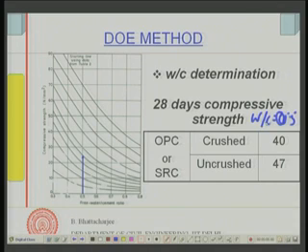The best way is to do a trial mix, and in the trial mix what do you do? You cast any workable mix with water cement ratio 0.5.